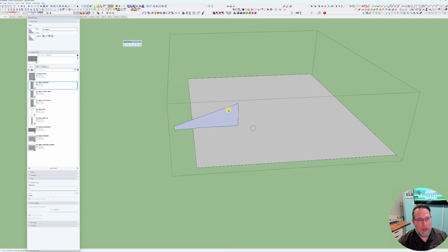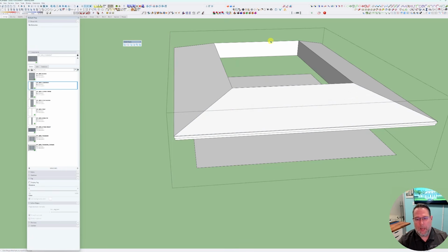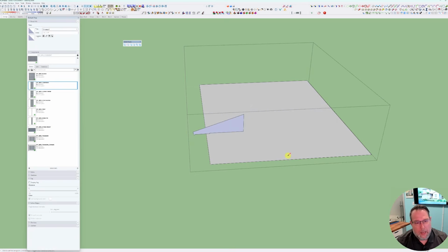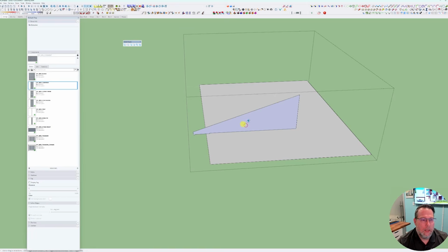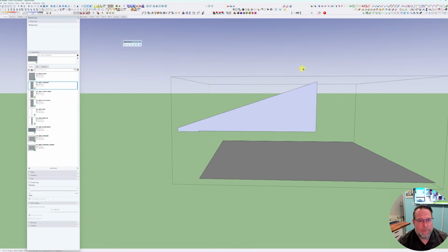Now I can do the same thing we did, but I'm going to try and play the chess game here and think through this, making it a little bit easier. I'm going to undo. Since this is just a pure rectangle, I'm going to take my shortest edge and draw a vertical line, and touch my angle because that will create the perfect peak. Then come down, and we'll draw this line all the way across, and we now have an exact size of my roof to the small point.